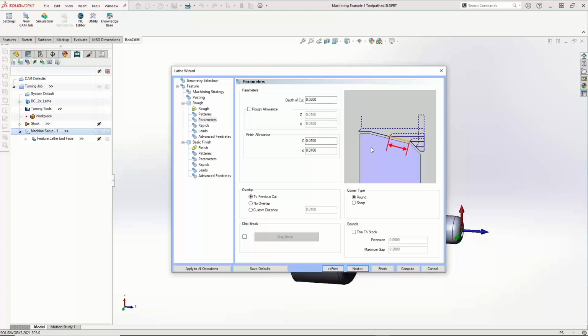You're getting rid of all the abrupt, sharp edges you might be leaving just running a tool into it. It's like if you've ever done a zigzag on a mill and you do it inside of a pocket. So you just zigzag back and forth when you do your cuts, you'll end up with just like an end mill mark and an end mill mark and an end mill mark. That's what the no overlap is essentially doing. You're not finishing it after that. So it's just something to do. It doesn't add too much time out of the job. I mean, it can. It all depends on how big the part is. But it'll make it easier for your finish tool coming in later on.